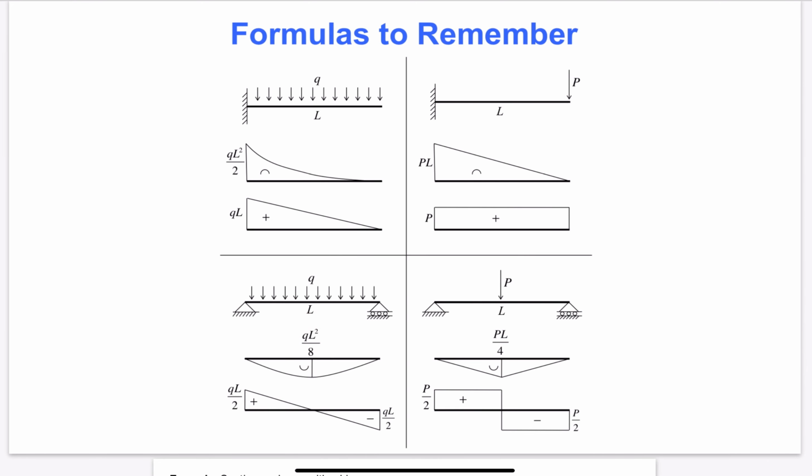We derived this result in an earlier video in this short course on equilibrium. In fact, we have already seen that the parabola for the cantilevered beam above is also a QL²/2 parabola. Again, the simply supported beam case is important because analyzing it reveals how the bending moment varies between any 2 points of any beam case.